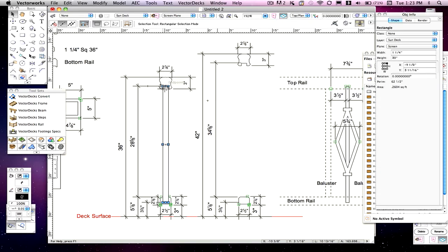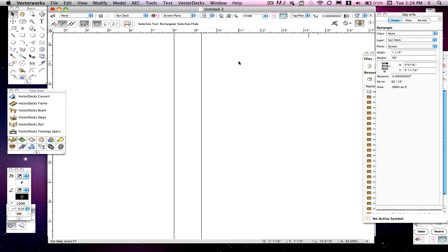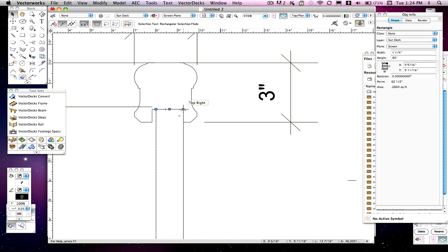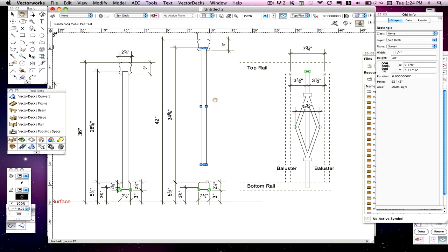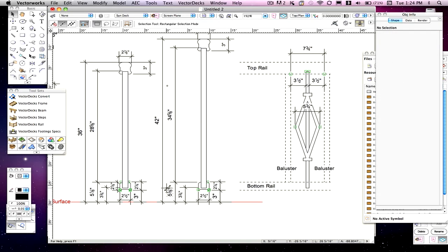So I'm going to take this and duplicate it, and let's drag this top corner over to here. Make sure I'm in that pocket. It doesn't want to drag sometimes. The handle plays around with the dimension. Here we go. And in all likelihood, because it's just 6 inches taller, we can probably just change this to 36 and it should work the same. Yeah, see, it does right there.